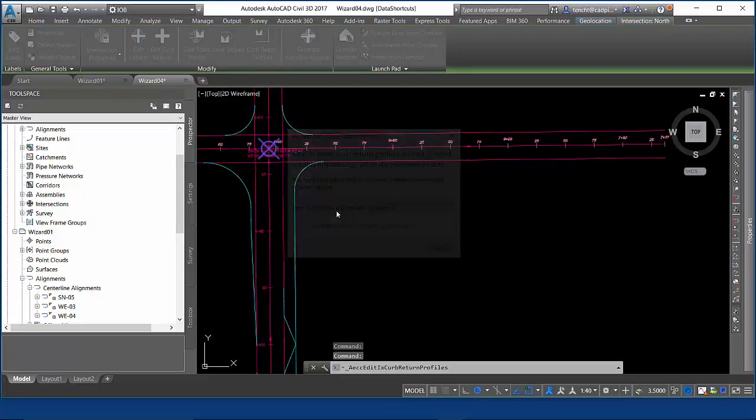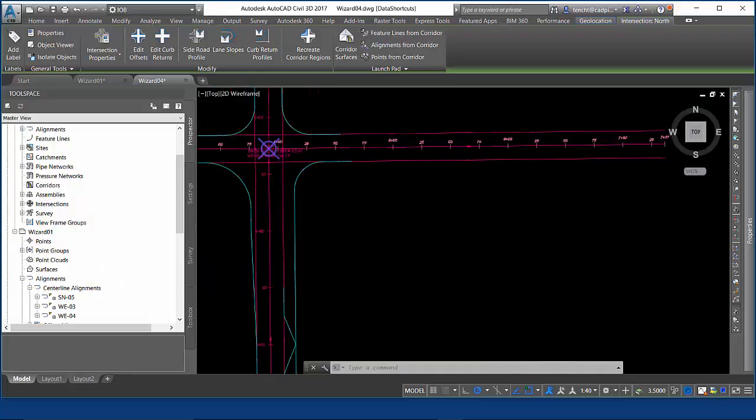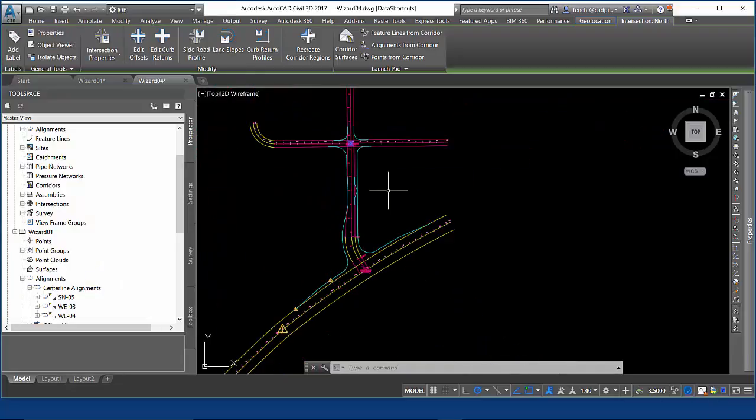Curb returns, create the curb returns. Just use default values here for all four. I generally like to page through. I did do some transitioning, but we have our verticals now all done. So I hit intersection 1, hit intersection 2, went through all the vertical panel and got it all right. And now I need to create my quarter regions.